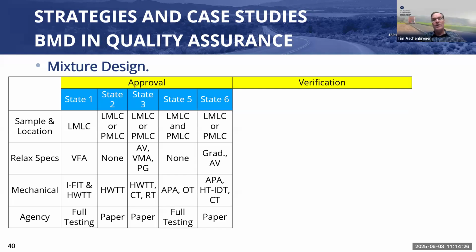Yeah, that's a good question, Ellie. And I would hearken back to our webinar 2. Webinar 2 out of 5 is on validation. And validation is when you're selecting your mechanical test. You want to select the test that matches the distress you're looking for. And then you want to set a criteria or a threshold with that test that matches actual pavement performance. So when you're running